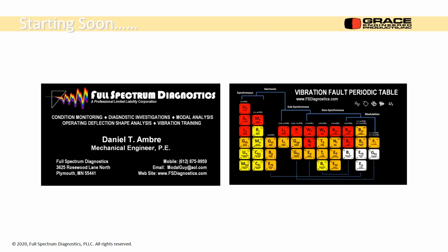I might be talking out of place, but I think you can get a node that's a single axis node that might be cheaper, and do a triaxial on some and do a single axis on another. I'd have to look into that. I'm not fully versed on all the different product lines from Grace yet. But that's the biggest problem, being able to cover multiple bearings with fewer transducers. You'll miss something.